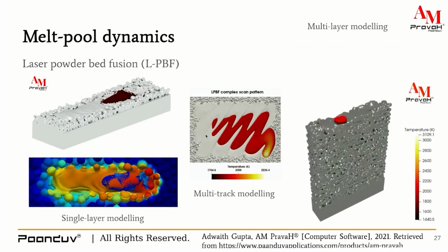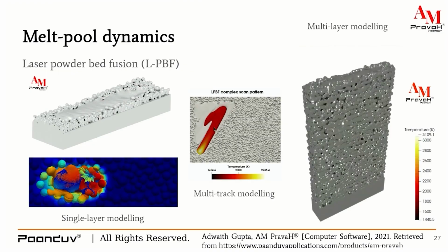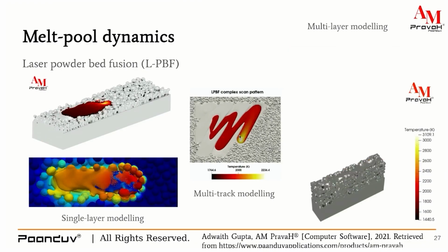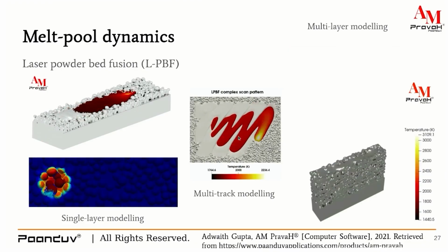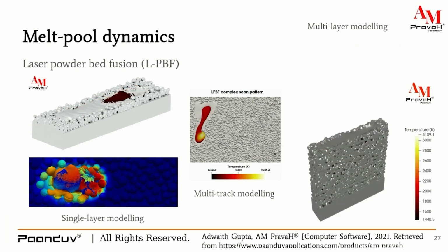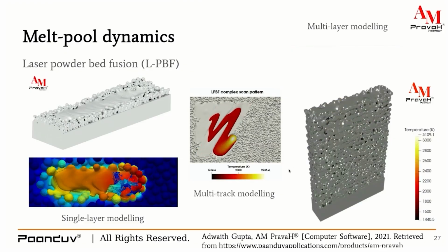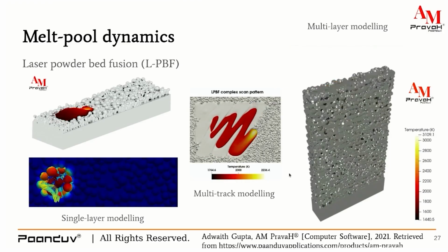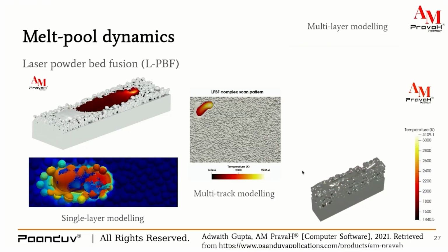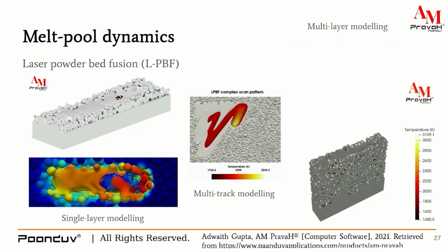There are pores created successively as the laser moves from back to forward direction, and there is a clear ejection of vapor happening in the system. We have modeled the similar system, and we have seen the evolution of keyhole as well as the progression of keyhole in the similar manner. As the keyhole moves further, it leaves lot of pores behind, and it leaves the vapor depression at the end. A persistent keyhole can be seen from start to end from the top view in this animation.